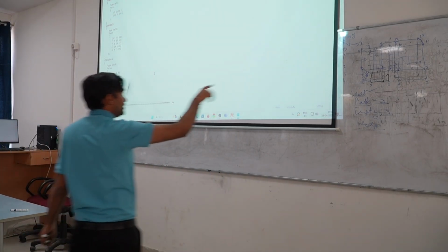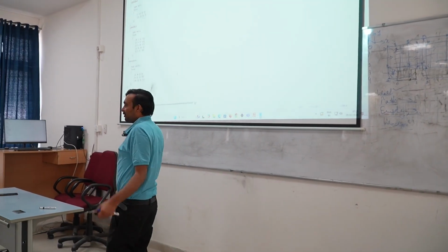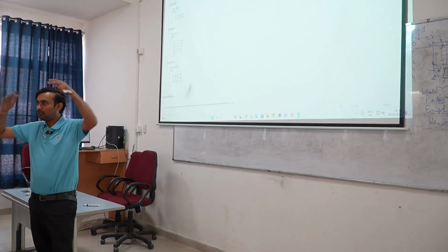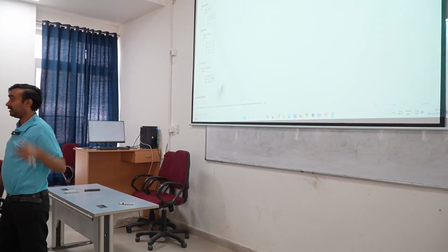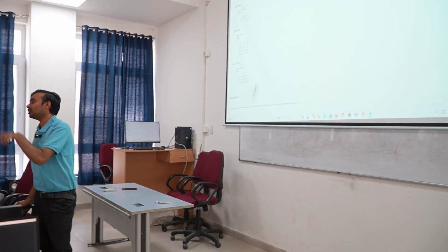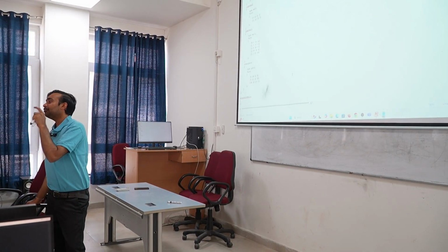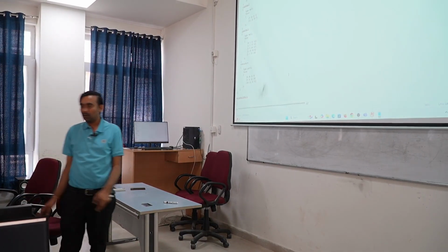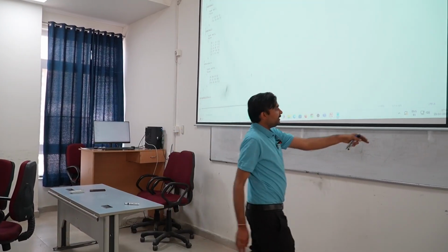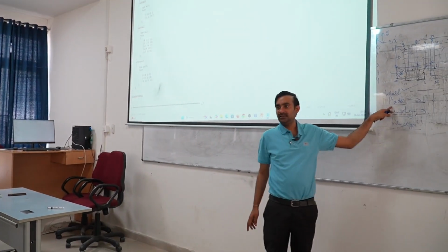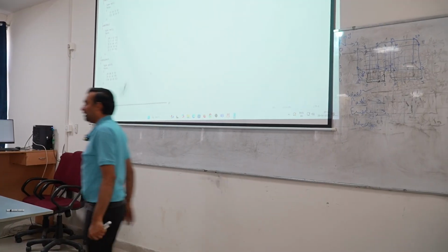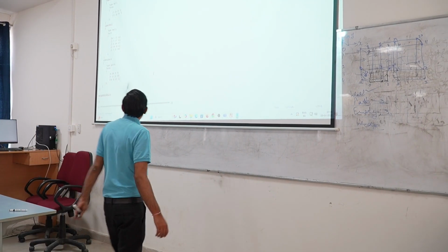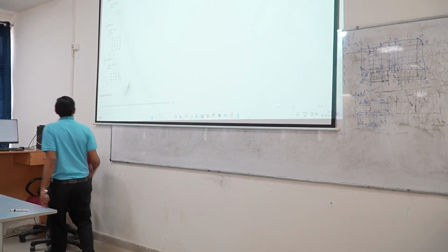Likewise all are defined, but an important point: when I specified the geometry, I told that through the top something can go out and something can come in. So this is not a solid wall, but a permeable boundary through which material can come inside and go outside. So I need to define its type as patch. Instead of wall, I will define it as patch. Okay, that is done.